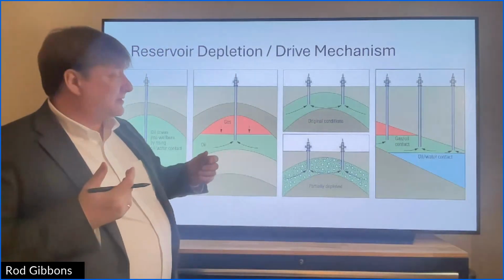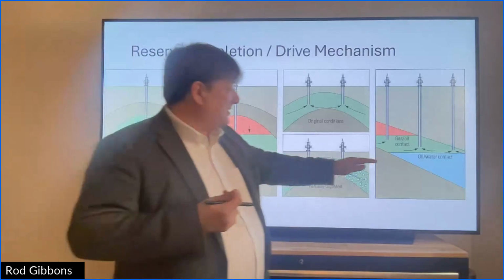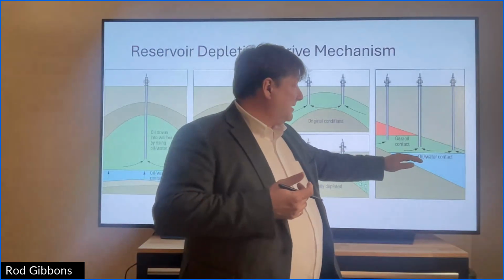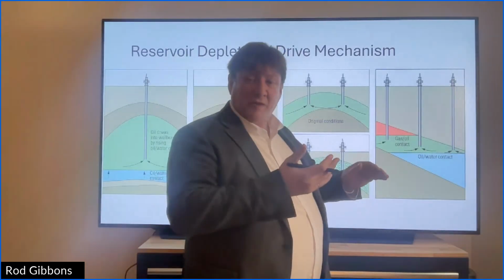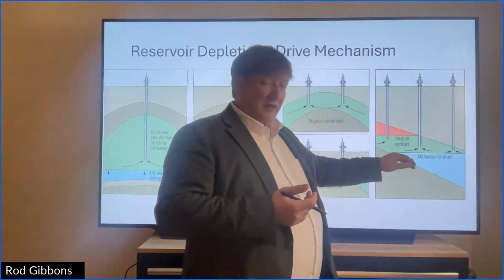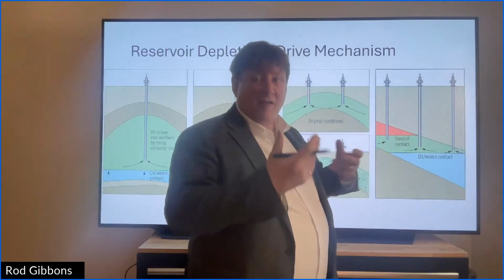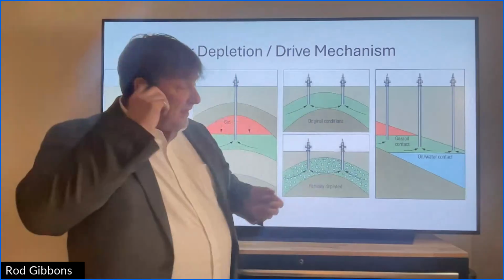One of the good things about water in the reservoir is that it can provide pressure support. But the problem is eventually this water is going to reach the well and you're going to have a heavier fluid that you have to lift.